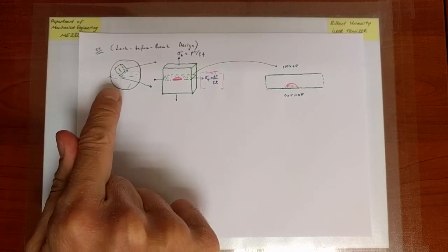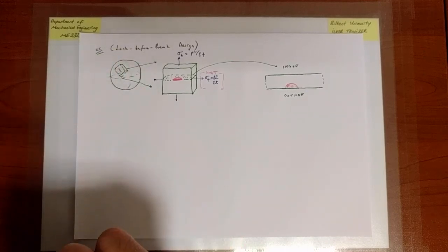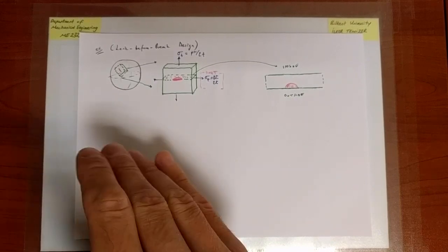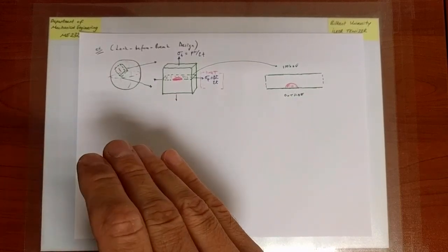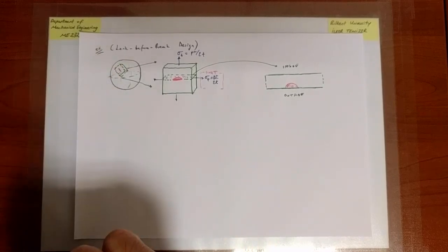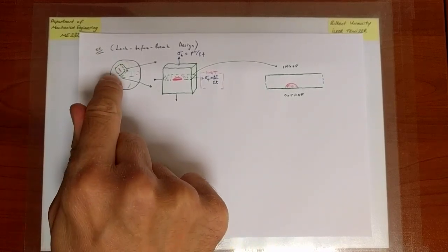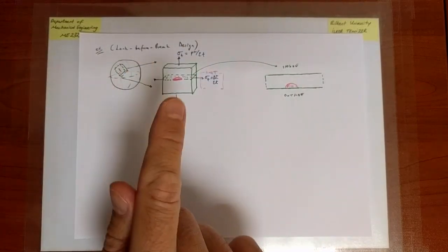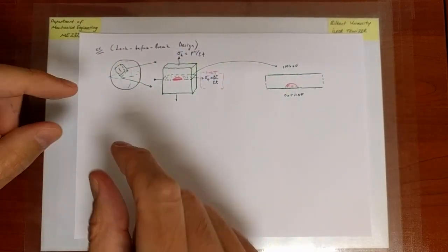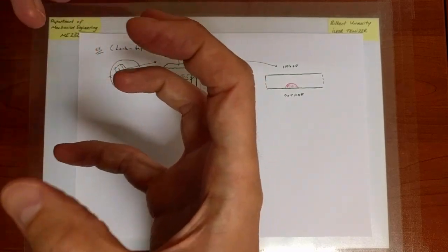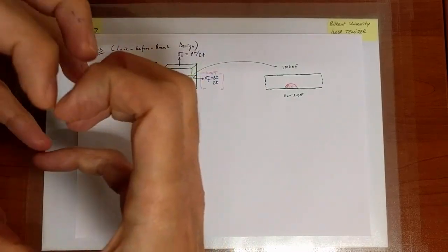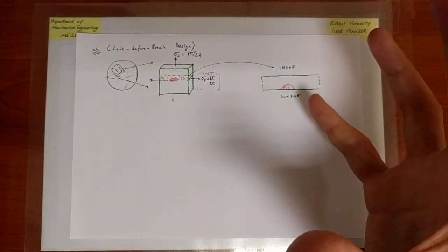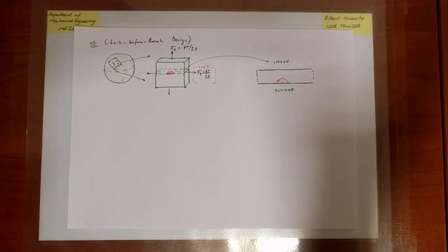So I like to make sure that this pressure vessel is free from any possible fracture. The reason I want that is because when fracture occurs, it's catastrophic. This crack will very rapidly propagate, and in some strange fashion it will branch into different portions. It will split the surface, the sphere, into smaller portions, and those portions, under the action of the internal pressure, will rapidly move in different directions.